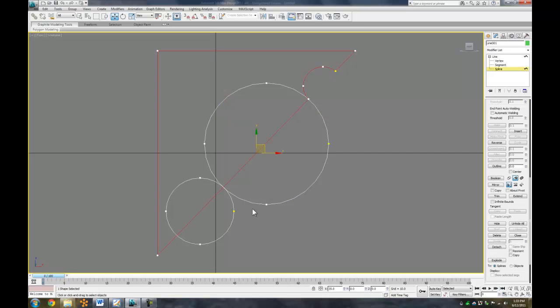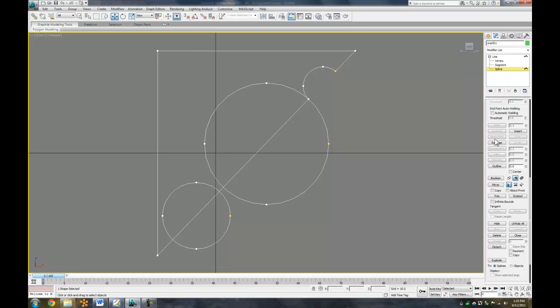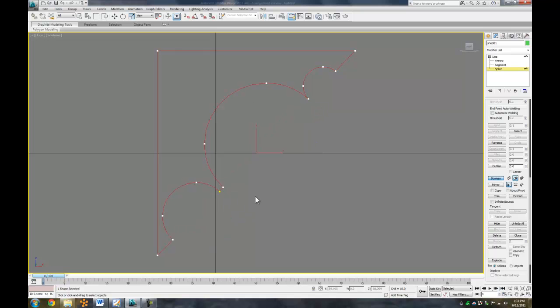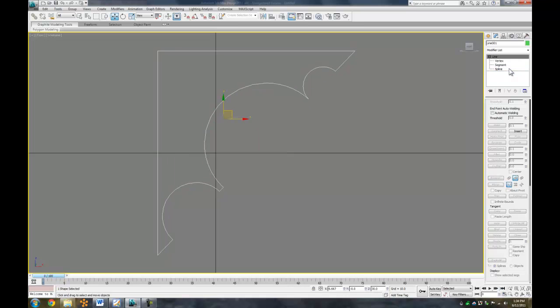So one of these circles was off a little bit. And we go ahead and do our Boolean. You can see that we have 2 vertices that are off of each other. We want them sharp like this, as you would have lathing wood. So we're going to go to vertex. We're going to select those 2 vertices. Now we're going to do something called weld, and it's welding basically 2 vertices. So we have the 2 vertices selected, and with this weld you could pretty much go pretty high. Just go about 50 there, and just click weld, and now you have some nice vertices.